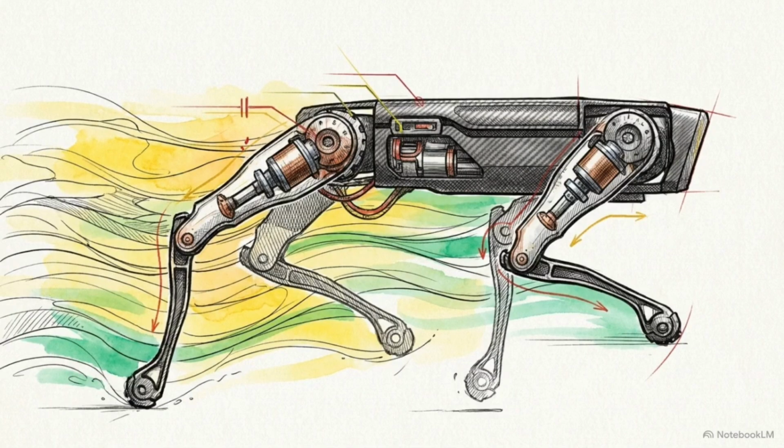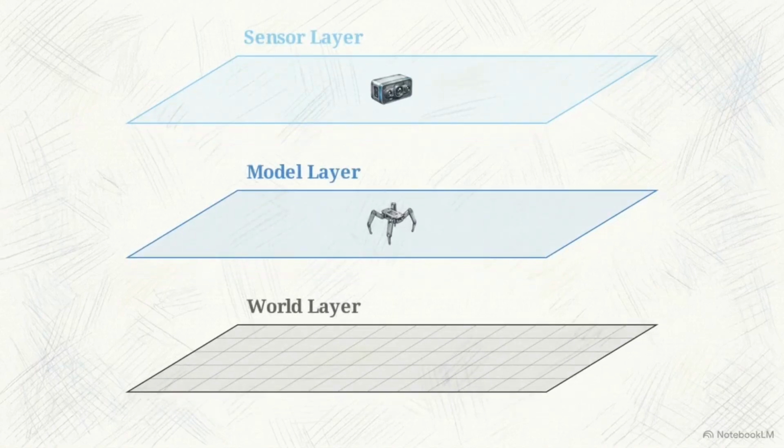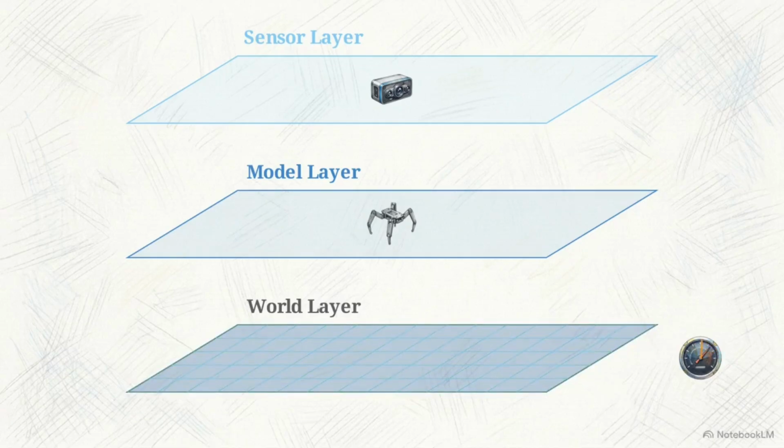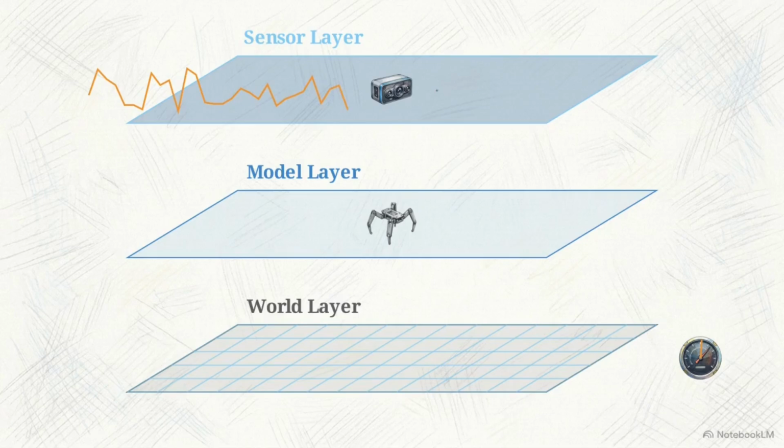Finally, model plugins act as the primary gait controller, scoped specifically to the robot's joints. For quadruped gait control, you will spend most of your development time engineering the gait logic to respond to changing ground conditions from the world plugin while receiving filtered orientation data from the sensor plugin.